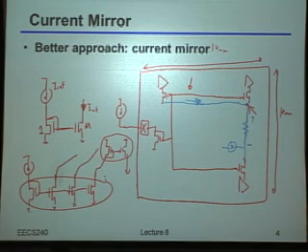Okay? So in other words, anytime you have to cover space, you should really route the current. Because again, once you send the current into the diode-connected device, the diode-connected device will figure out, well, okay, if I have a certain current flowing into me, then based upon whatever my local supply voltage is, I'll create a gate voltage referenced to that potential. Okay? Does this make sense to everybody?